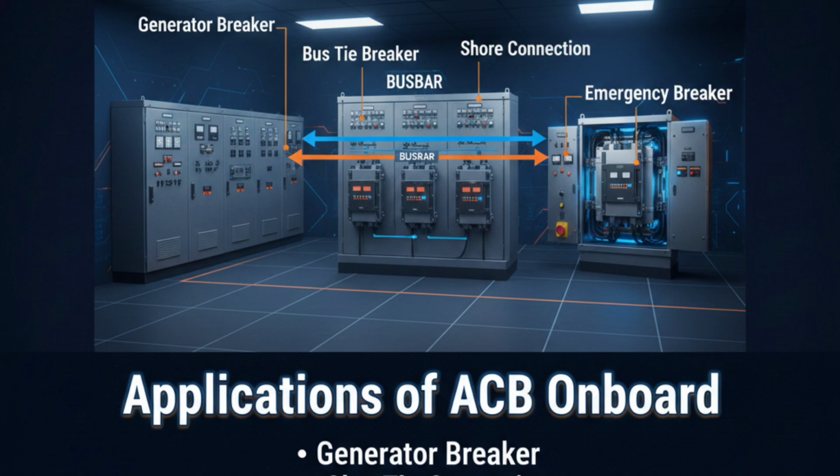Bus tie ACB connects two bus sections. During maintenance or fault isolation, the bus tie allows flexible power distribution. Shore connection ACB connects external shore supply to the ship system when in port. Emergency switchboard ACB protects emergency generator output. All these breakers look similar but their protection settings may differ depending on rating and function. Interlocks are also provided. For example, shore supply and generator cannot be connected together without proper synchronization. Understanding where ACB is used helps you understand its importance in system stability and protection.